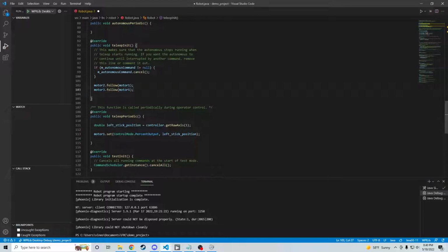An important thing here is when you're testing multiple motors inside a gearbox, you want to do one of two things. One is drive them really slowly at first and look at the motors and make sure that the colors they're blinking are the same. Green lights mean that it's driving forwards, I think, and red lights mean that it's driving backwards. So if you see red on one and green on another right next to each other, that means they're driving in opposite directions and something's wrong. I'd stop that and call one of us over to figure it out, because you don't want to drive it fast. You want to drive it really slow. You just want to push your stick just barely forward.